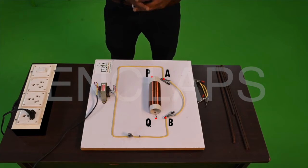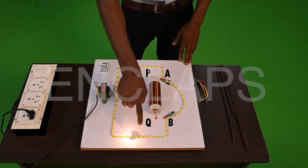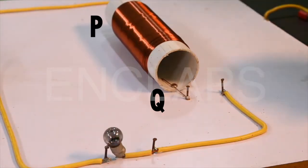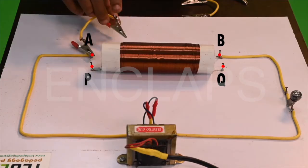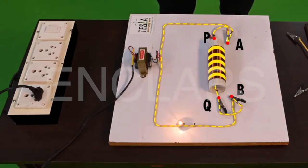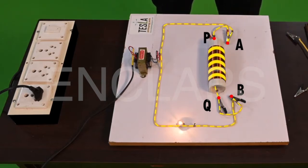Let's do the experiment. When the switch is on, current flows through the wire AB and the bulb glows. Now, let's remove the part AB from the circuit. Then, the circuit is open and the bulb does not glow. Now, we are connecting A to P and Q to B, thereby completing the circuit. Now, the current is passing through the solenoid. Here, we can see that the intensity of the bulb decreased.